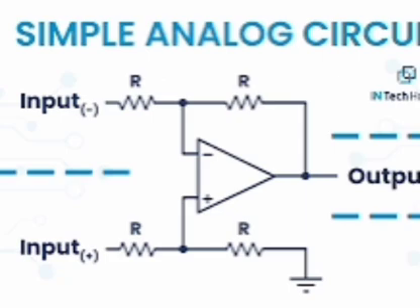pure AC input, C in parallel with RL output. For half wave rectifier, ripple factor R equals 1 by 2 root 3 F naught RLC, with 2 root 3 F naught RLC in the denominator. Peak to peak ripple voltage VR equals IDC by F naught C.